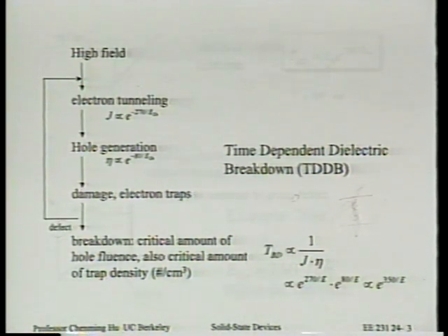It so happens another student has studied this question, and Elise Rosenbaum actually got a Best Student Paper Award at IEDM some years ago. She's now a professor at the University of Illinois. And the answer is yes and no. If you just apply a unidirectional pulse, the answer is yes. It's just a matter of a duty factor. If you apply a bipolar pulse, that is, one pulse is positive, one pulse is negative, the result can be quite different from the DC, and we can address that after we finish talking about DC, which is a simpler case.